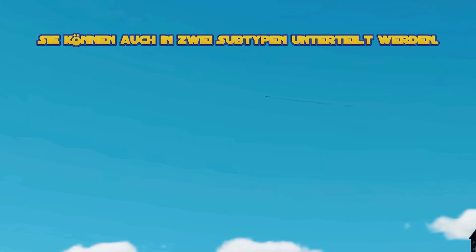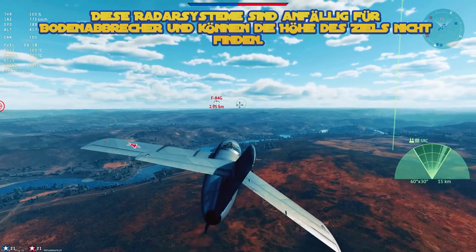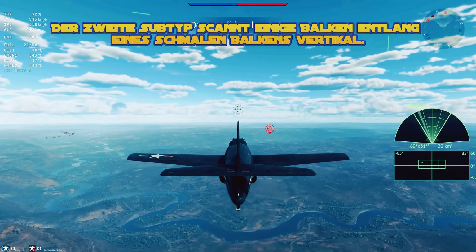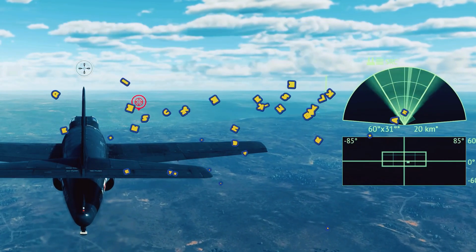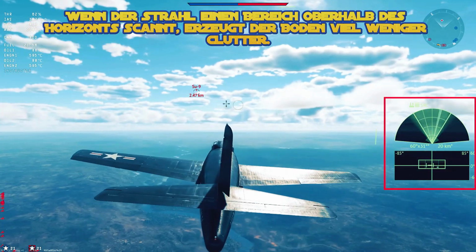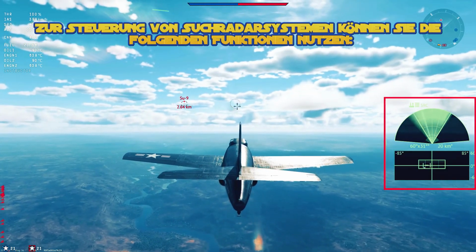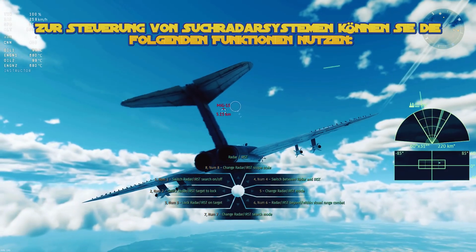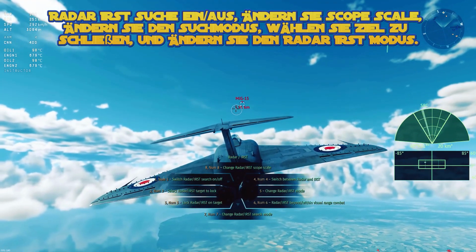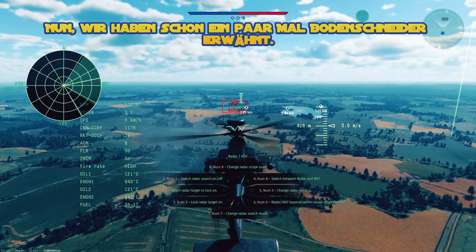They can also be divided into two subtypes. The first one scans the whole sector vertically using a wide beam. These radar systems are susceptible to ground clutter and cannot find the target's elevation. The second subtype scans a few bars moving along a narrow beam vertically. When the beam scans an area above the horizon, the ground creates much less clutter. Moreover, these radar systems can find the target's approximate altitude. To control scanning search radar systems, you can use the following functions: Switch Radar IRST Search on/off, change scope scale, change search mode, select target to lock, and change radar IRST mode.